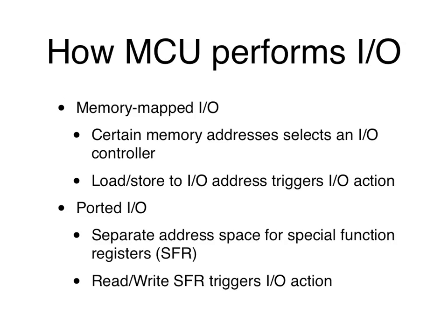It's 2 to the power of 16, which is 64K. Now, if you have a memory address that is 32 bits, then how big is the memory space? It's 2 to the power of 32, which is 4 gigawords. And a lot of times the unit of a word is a byte, so it's 4 gigabytes.